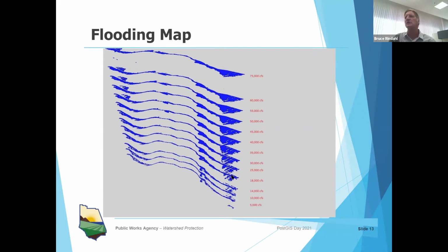And as you gradually go up in flow values, in this case, 25,000 CFS, you can see the inundation boundary gets larger and larger until we get to the very large areas, including all the extensive inundation at 75,000 CFS for this particular location. So we have a whole library of values that include the GIS boundaries stored in PostGIS.